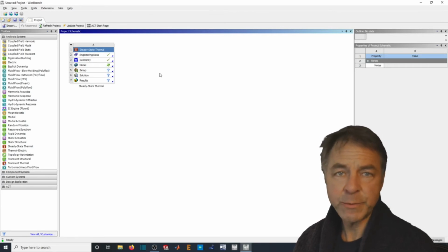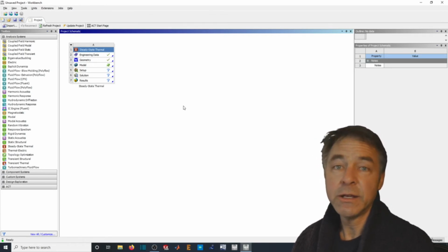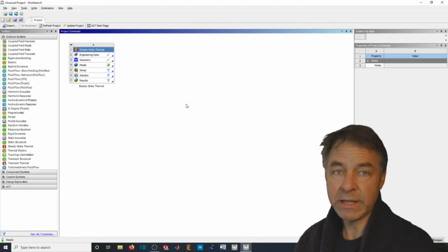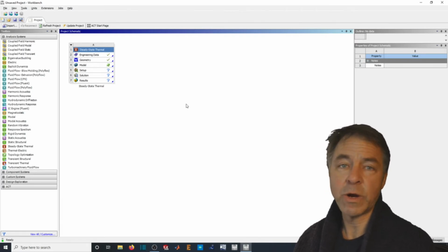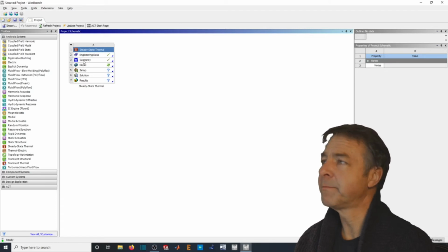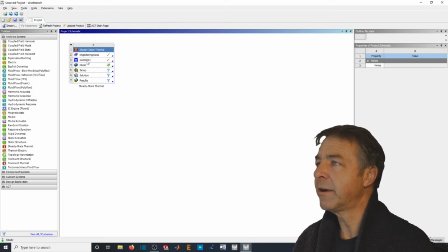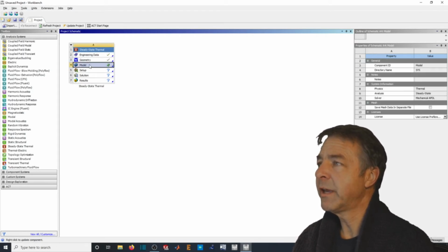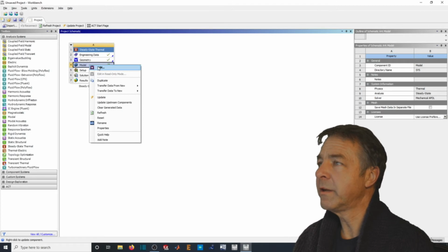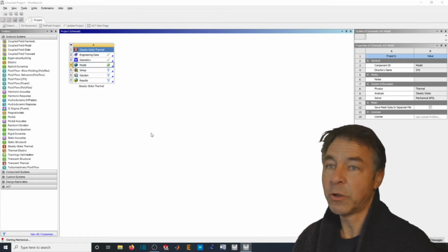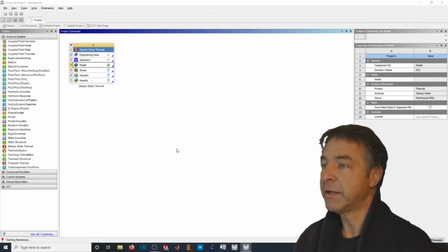In order for the two-dimensional to work, annoyingly, it has to be two-dimensional on the XY plane, not the XZ or YZ plane. So be careful of that. So the check marks up here show that we've got our engineering data and our geometry right. Now we can right-click here, and we can edit the model, and this will open up a new window of ANSYS Mechanical.